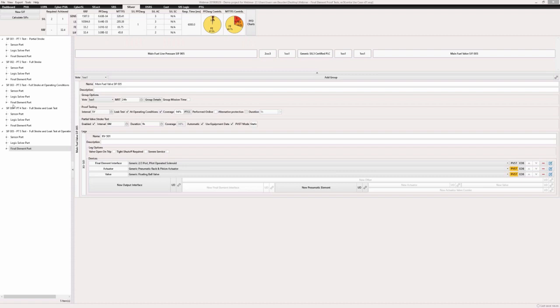Is there any recommended safety margin for PFD average? There's not, at least not that I know. One of the things that is required in the standard is that we use realistic failure rates, that we use certain confidence limits on failure rates, which is the case for the equipment in our database. So I'd say that if, let's say, I need to achieve a SIL 2 and I end up with a risk reduction of 101 in my calculation, then I would feel comfortable saying I've met SIL 2 because of the failure rate confidence level. So there's not, at least to the best of my knowledge, a safety margin that would be applied.